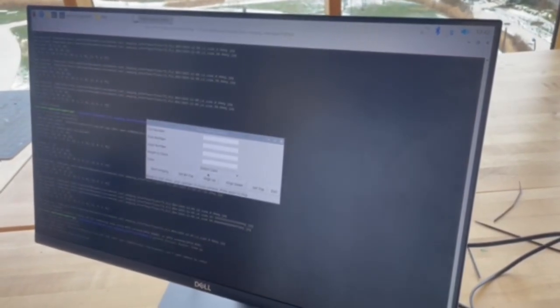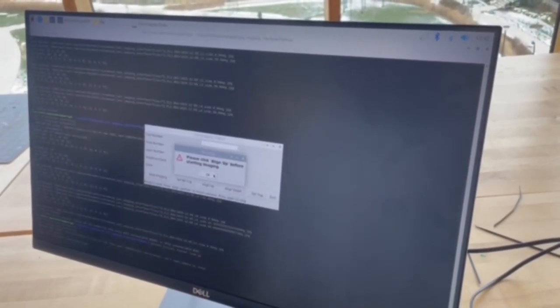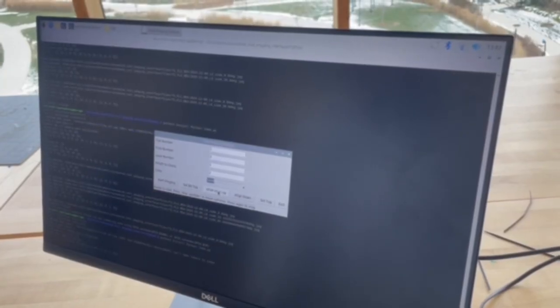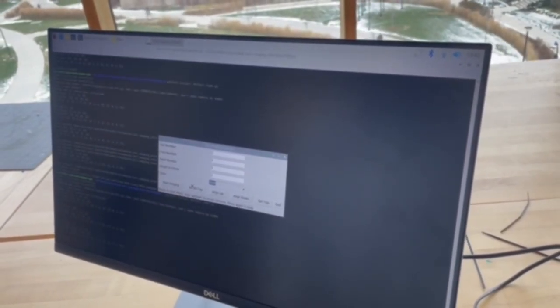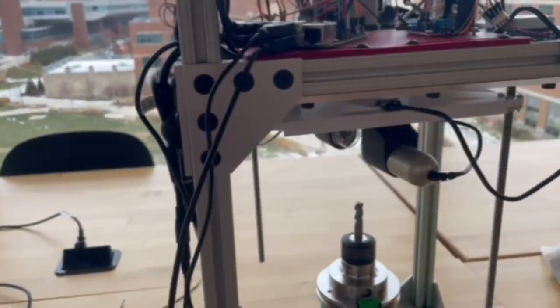To use the imaging station, first put the 3D printed tool holder into the bottom slot. Second, enter the tool information into the user interface. And then after you've done that, adjust the height of the cameras so that they are at the top of the tool bits. Then hit start and wait for the system to capture all the images of the tool.